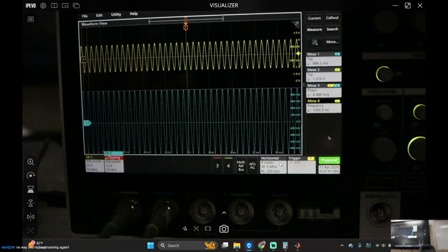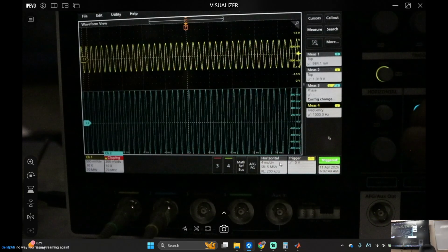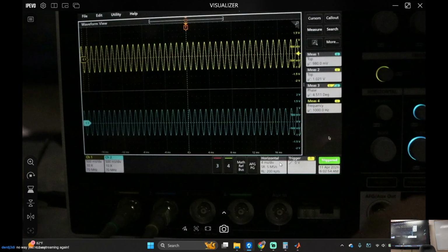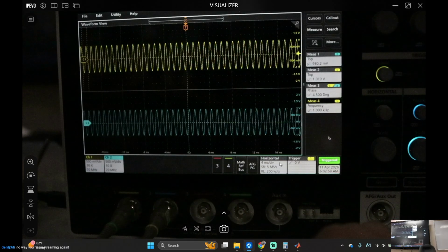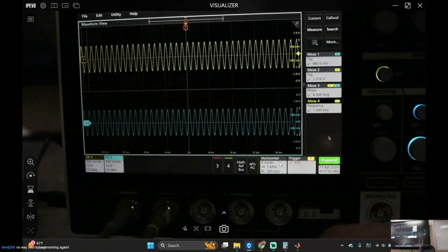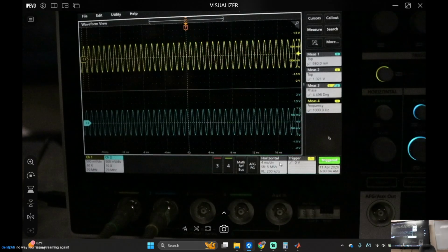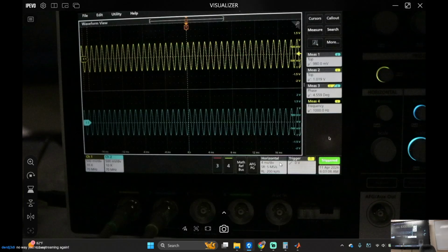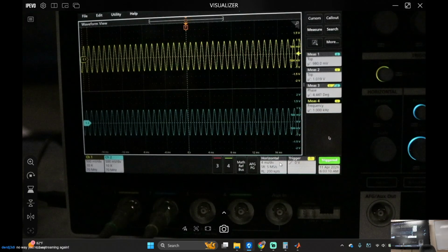And then let me just press this right here. And then what's the output voltage? 980 millivolts, right? Divided by 1. And then do 20 log dB, right? Does that make sense? And then you guys are going to draw your Bode plots, okay? Is that going to be a fun lab for everybody? Are there any questions for what I'm trying to expect from everybody?